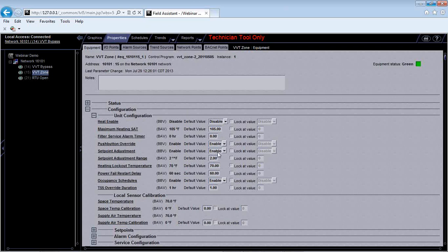And you saw before on those sensors, there's different types of set point adjustment. You can do slide bars or digital displays, but this is actually where you can prevent your customer from adjusting set points and occupancy locally in each zone. That's something that you need to figure out based on who your customer is, what the application is, if they have the ability to do that or not.